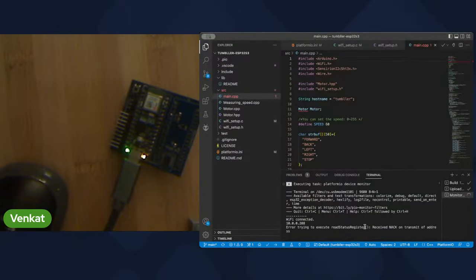He doesn't need to press the black button at the same time as the white button. No, that is only needed once you have programmed it with the Arduino IDE, because it adds the USB CDC, and then it removes the JTAG from this USB. So the first time you have flashed with this config, you don't need to do it again.